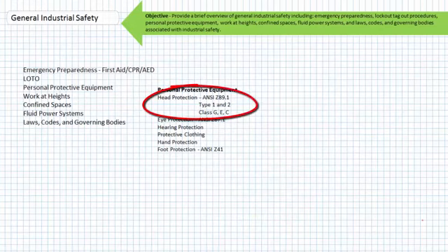Head protection. The hard hat's obvious purpose is to protect an individual from head injuries, notably dropped objects. People often assume the most common safety incident involving wind turbines is that of injuries sustained from falls. This is incorrect. The number one safety incident involving wind turbines is dropped objects. Safe work practices and a disciplined workforce that routinely tethers and ties off all tools, radios, or equipment must be developed. The hard hat protects an individual from this avoidable error.